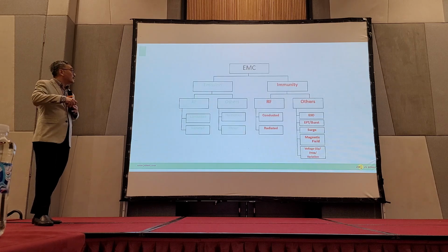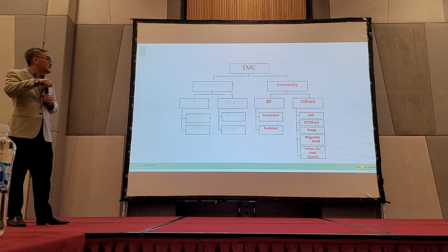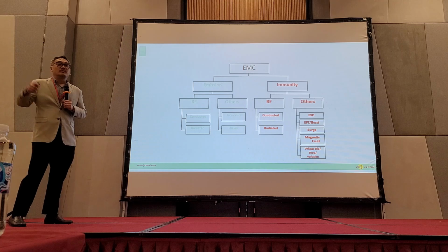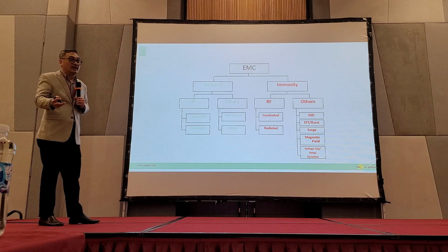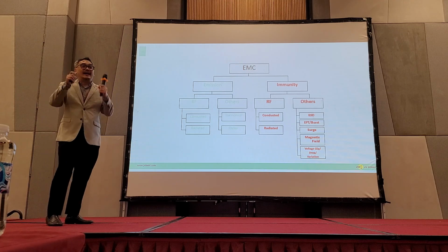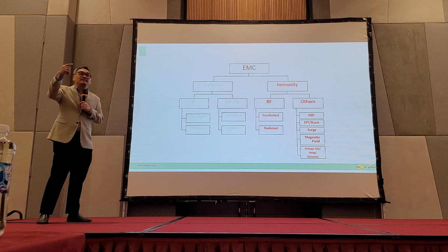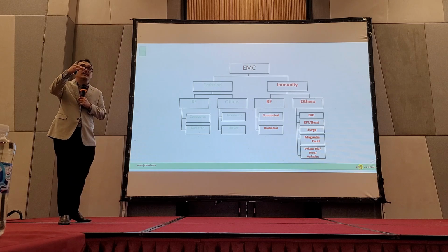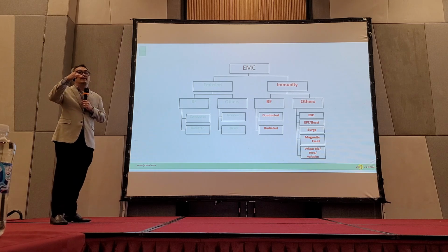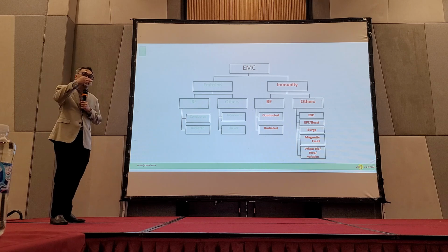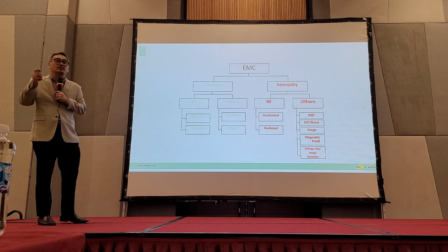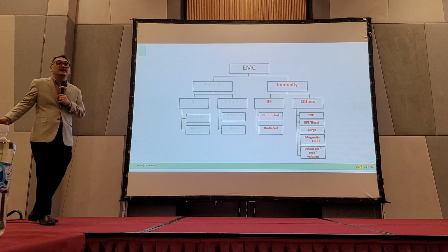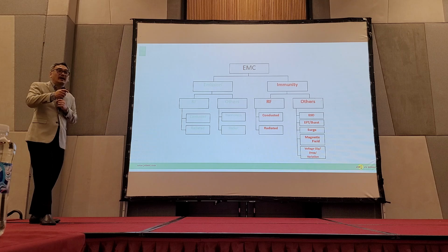So generally we measure the noise, and we finish. Now we inject noise into the product to see whether the product dies. Depending on the category, your product may not start, or it may auto restart, or it can fail, or whatever. It totally depends on the product standards. They have different criteria A, B, C, and D, so different products have different categories.